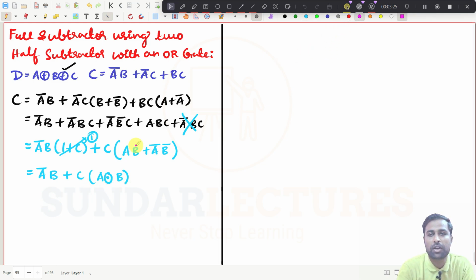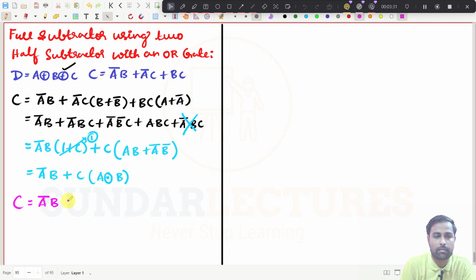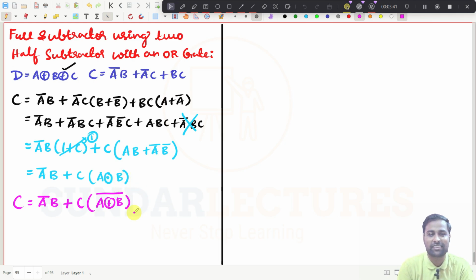So what you can do now, this one I can write like, this is A bar B plus C into A XOR of B, the whole bar. You have seen this one, right? This is XNOR, and the inversion of XOR can be written like this.